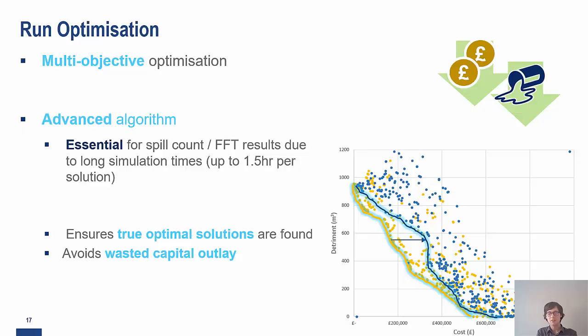showing the difference between two algorithms both presented as the best two software packages could offer. You can see that the blue method has not converged in the region where that arrow is, by the kind of lack of increased density of points on that Pareto front, as we showed on the previous slide. And that's a bit of a warning flag if we only had the blue results on their own, that something might not be quite right.